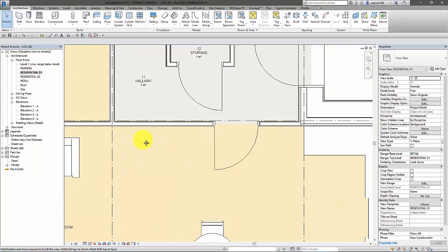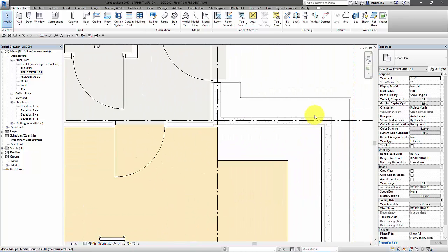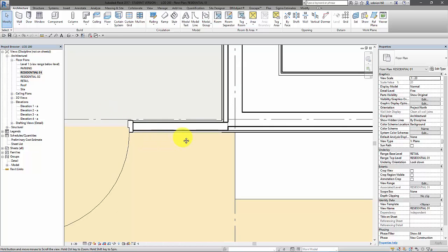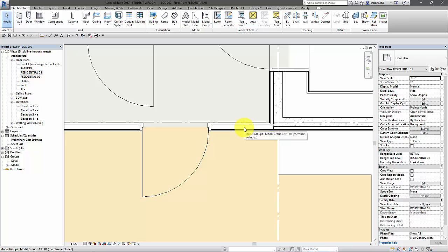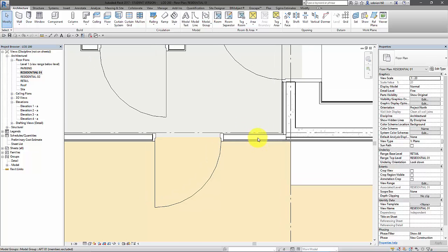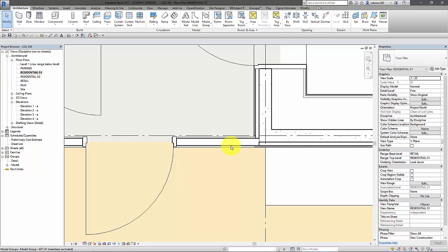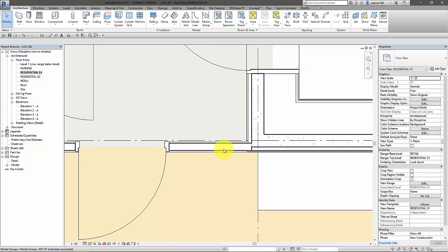But when we get to something like where there's an intersection between an external wall and an internal wall, if I just continue that along there, you can see we get this kind of awkward little corner here, which just looks terrible in an apartment scheme. So you have to visualize it from the point of view of the resident. What looks better? I mean, these are not structural walls. They would be built out of either metal stud or timber stud, probably metal stud. So it doesn't matter that we shunt it slightly out here because we're not slaves to the grid.